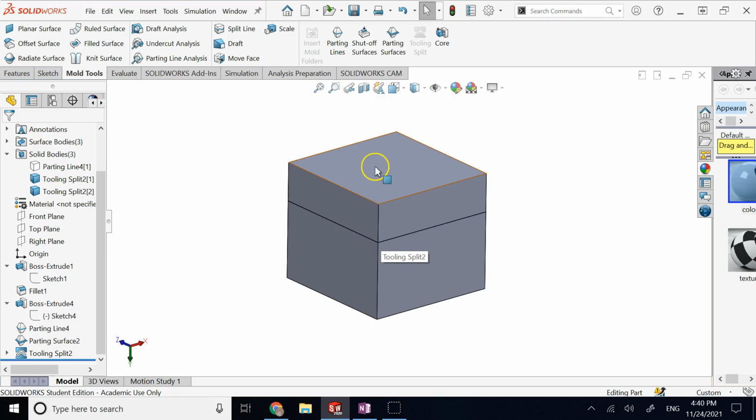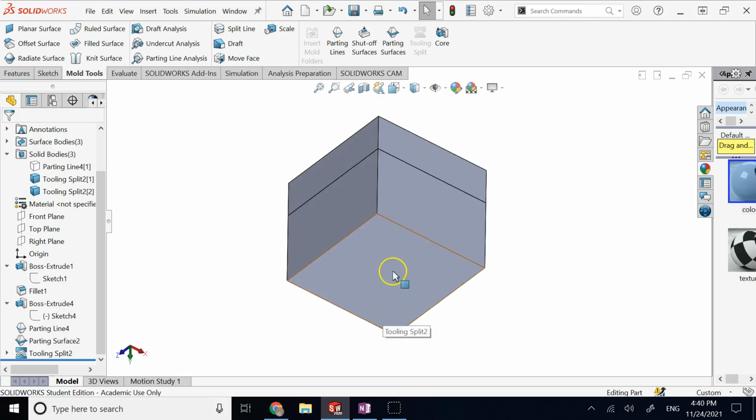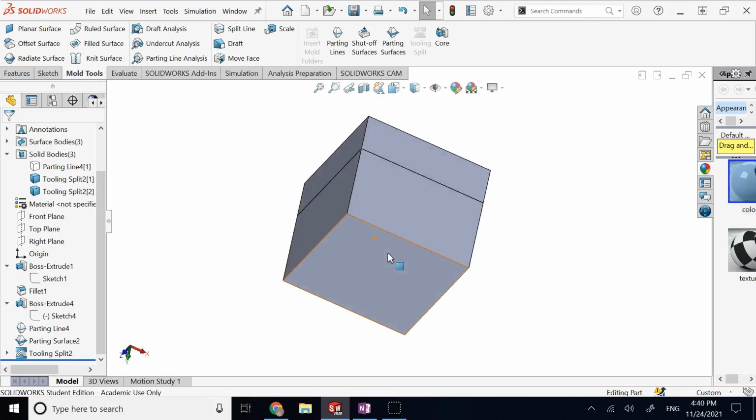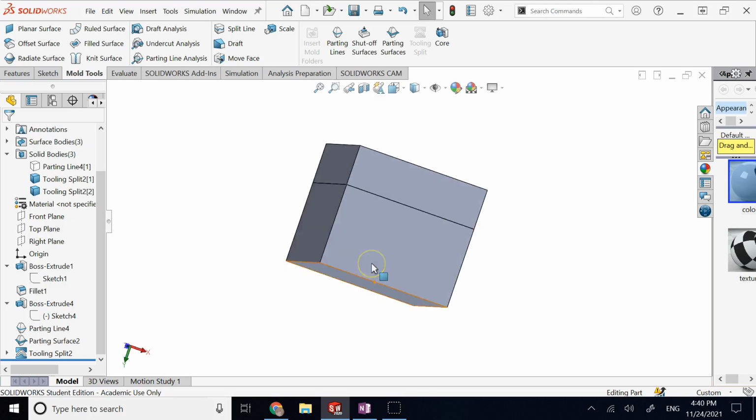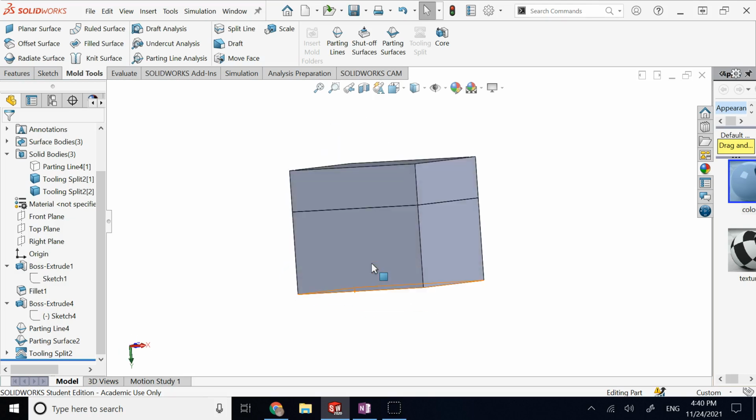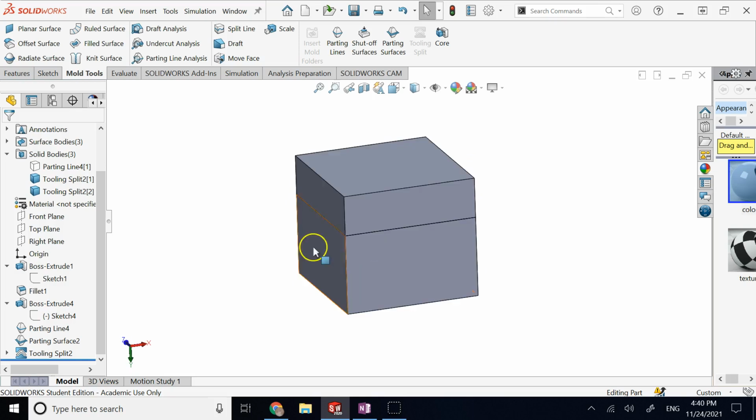And you also need a nozzle on the top part, so you can pour the molten plastic or molten metal into the mold. If there are several parts, you also need the sprue and the runners, and there are so many other things. If it is for injection molding, then on one of these pieces, typically the bottom piece here, you also need to have the areas for the ejector member, and there are so many other details that you need to add. So these are mostly really just the cavities.